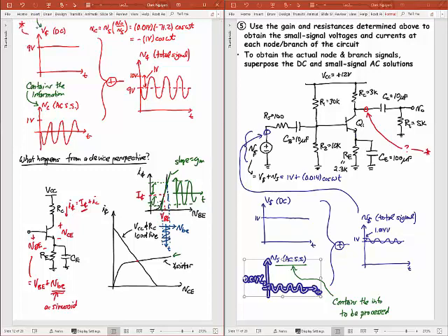So I should point at this and say that's for VBE, this large signal VBE right there. Okay? And so from that, I can go ahead and project down and across. Across is going to give me my collector current, capital I sub C, the bias point for my collector current. Down is going to give me my DC bias voltage, capital V sub CE.